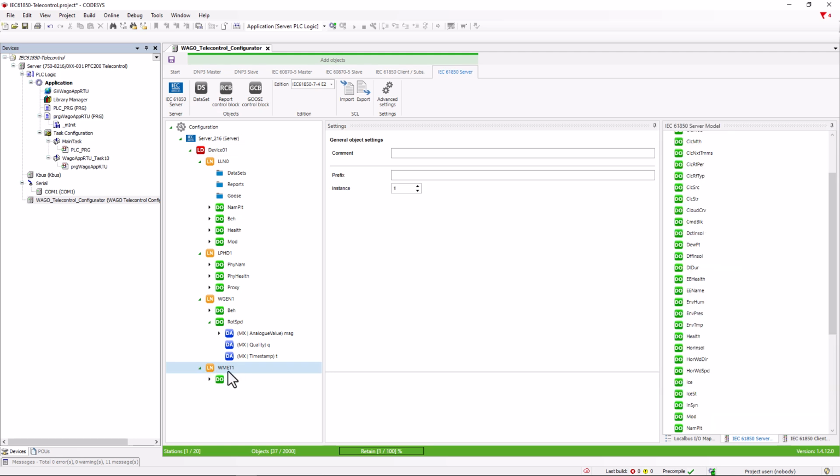For example, if we want to analyze the wind speed, we need to attach the wind speed data object to WMET. In the list of possible data objects, we find two for this purpose: the horizontal wind speed and the vertical wind speed. Since in most cases there is only one sensor for the horizontal wind speed, we select the horizontal wind speed data object.